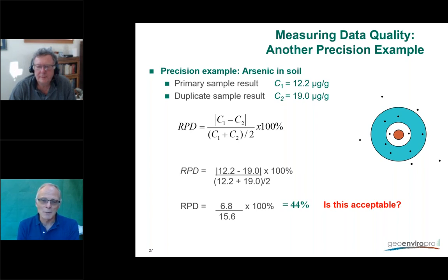Well, perhaps it's because you have paint flakes scattered around the site from sandblasting of buildings or structures that have been stripped of paint and then repainted. And then you would perhaps come up with a different or an additional analysis scheme where you look more at leachability because you're concerned about pathways. That's getting into interpretation of the data beyond the QA/QC.